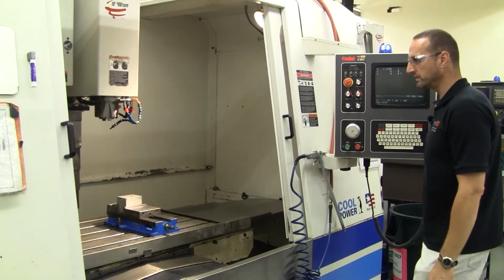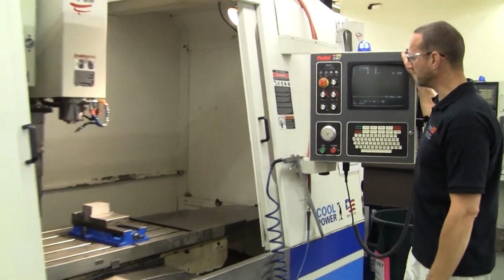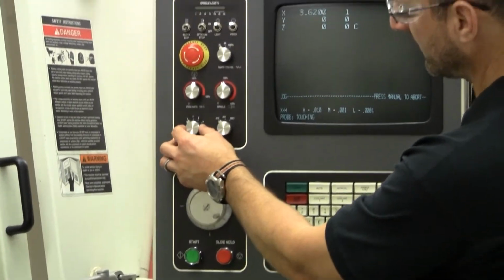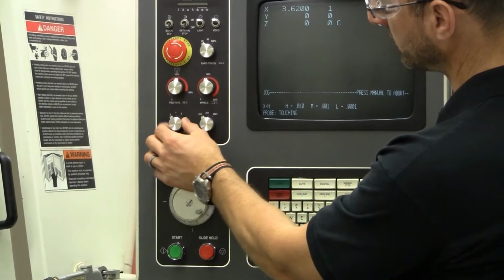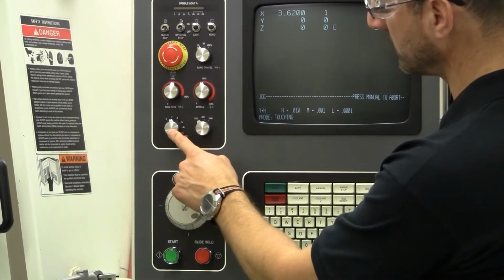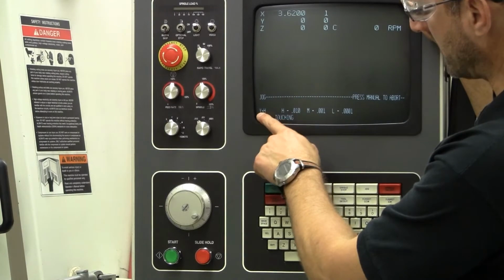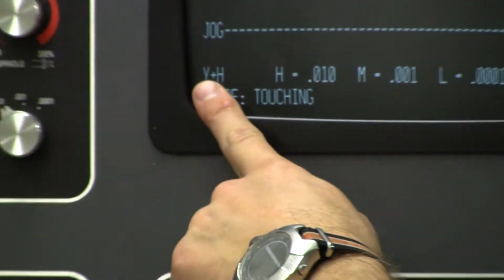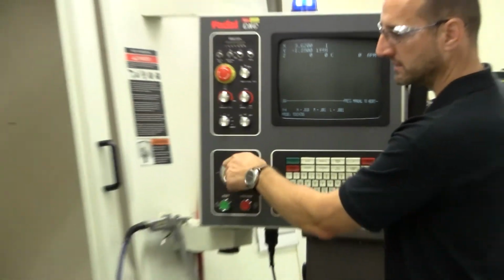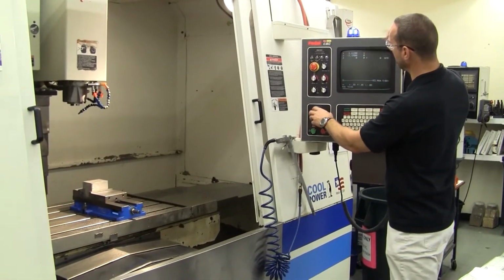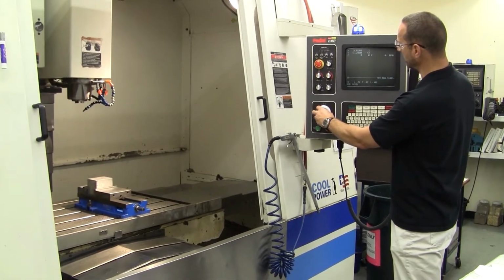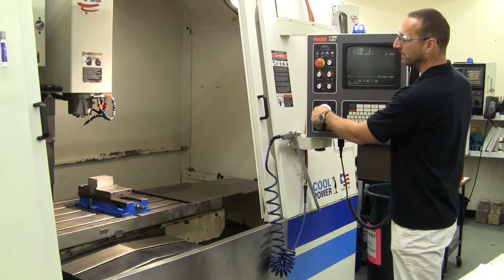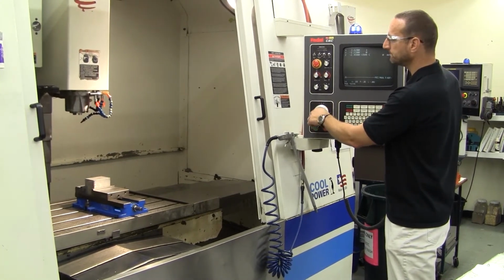If I want to switch to a different axis to move it, I have essentially two options. First, I can use the selector dial up here on the controller and switch this from X location to Y location. And when I do that, you'll note that the axis indication on the screen changes to Y. And now the Y axis is active. And again, I'm moving in 10,000ths of an inch increments. And of course, finally, Z allows me to do the same thing for the Z axis, like so.